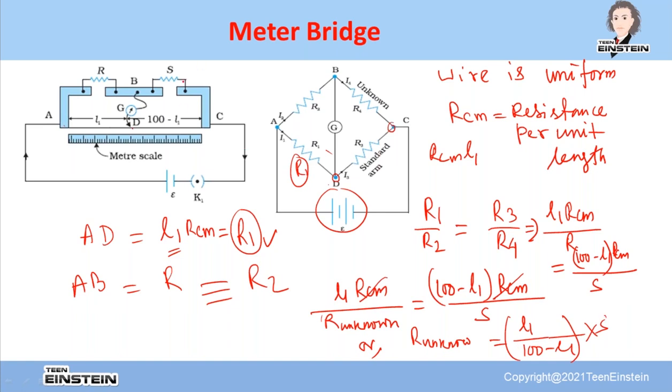It is written as standard resistance. It is actually a fixed resistance. Okay, here there is no change for this resistance. Once you connect, it will be fixed all the way. Where we are changing the resistance is over here. Okay, just by varying the length of the wire, we will be changing the resistance in the circuit and then finding out the null condition.